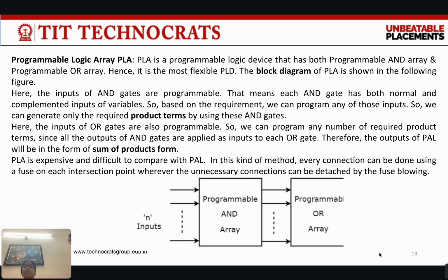Next PLD is the programmable logic array. Programmable logic array is a programmable logic device that has both a programmable AND array and a programmable OR array. Hence it is the most flexible PLD. At both the planes, OR plane and AND plane, it is programmable. The block diagram of PLA is shown in the figure.